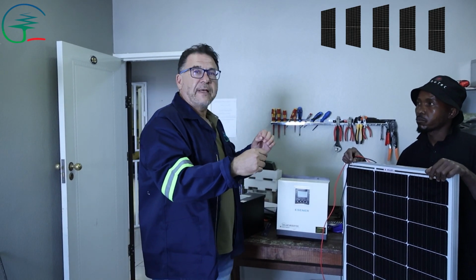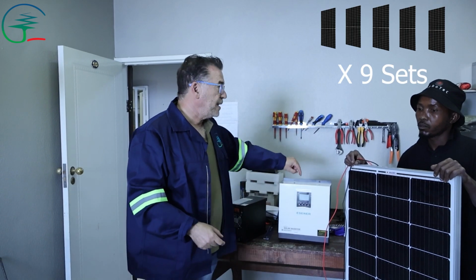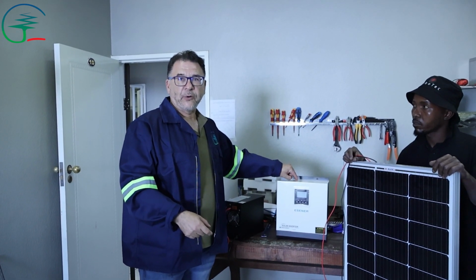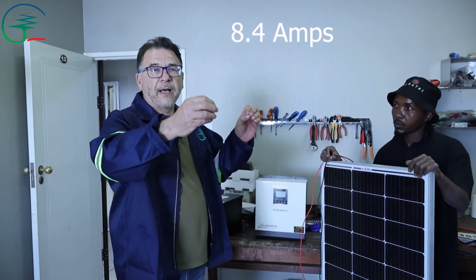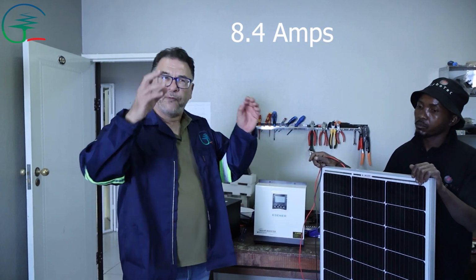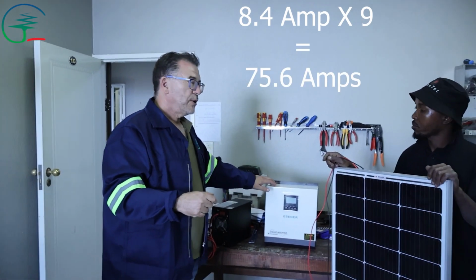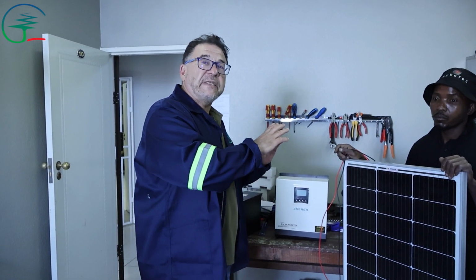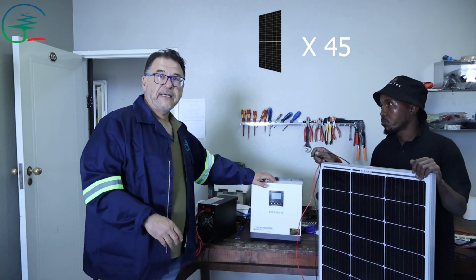Then you can have 9 of these sets or strings connected, because each set will give you 8.4 amps, and 9 of those comes to less than 80. So in other words, you can have 45 of these panels connected to this inverter.